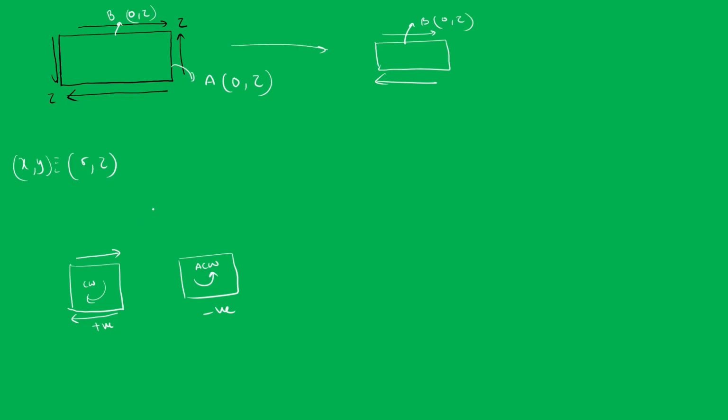And this one is anti-clockwise direction, so this face. Okay, so you can see, if I draw another replica of this particular figure, it is like that, and this is again moving in anti-clockwise direction. So this particular A face will have 0 comma minus tau. Don't get confused about why I have put minus tau here. Earlier I put plus tau, and then I showed you how we can change the sign. So that is minus tau.